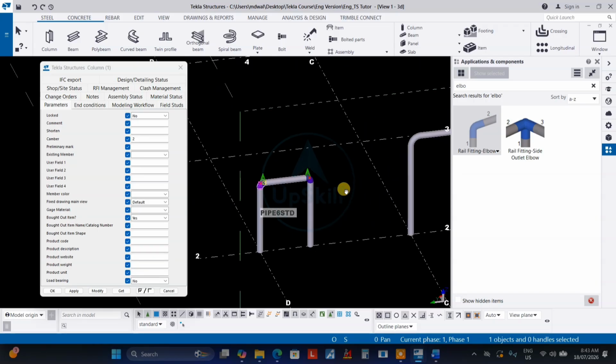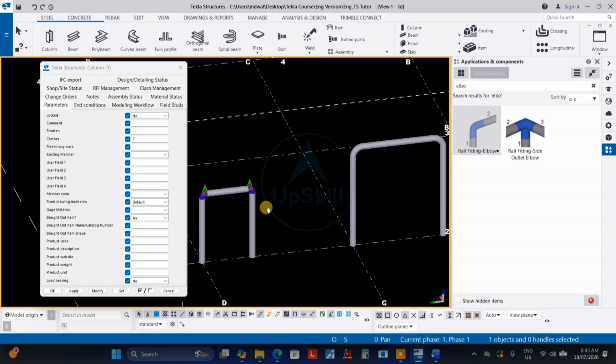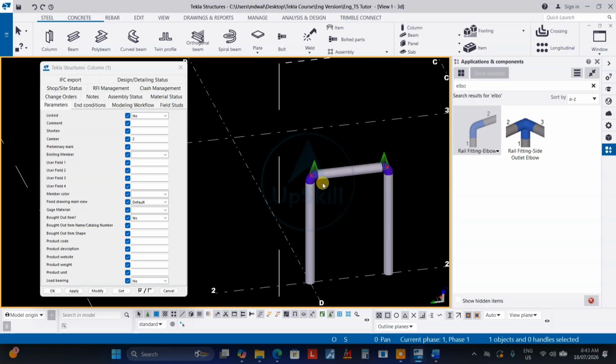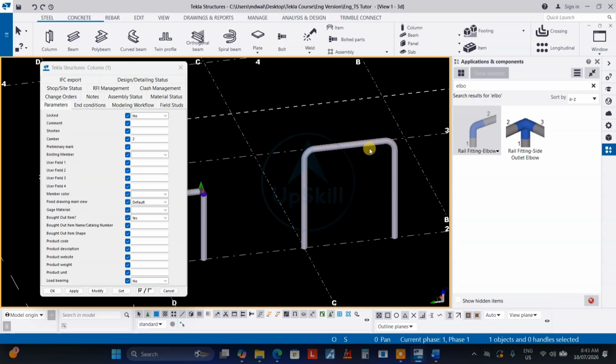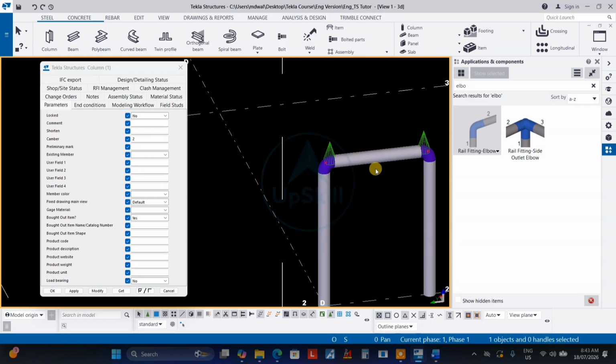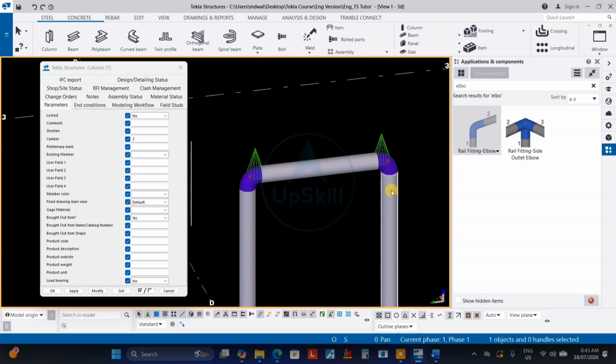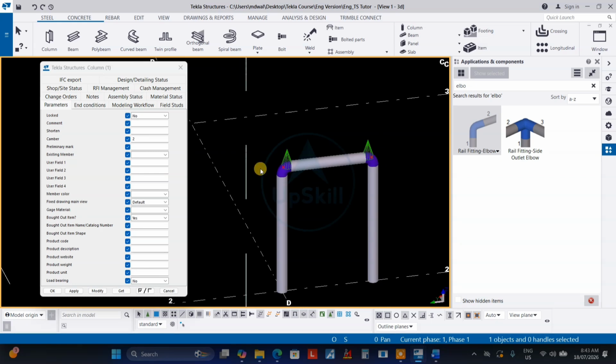Some fabricators have a bending machine for pipe and some don't. So he doesn't waste his time making it like this; they buy this and weld it from here, and they can achieve whatever handrail shape is required.